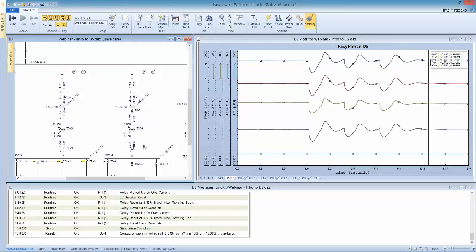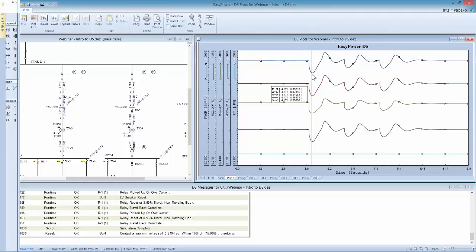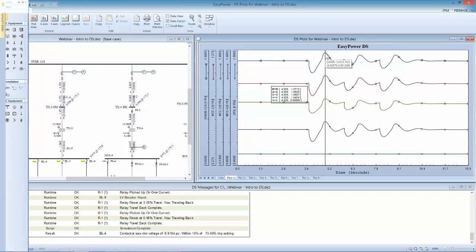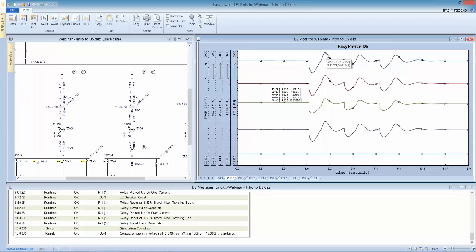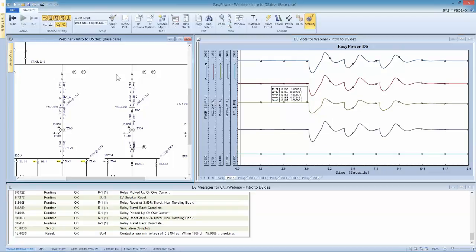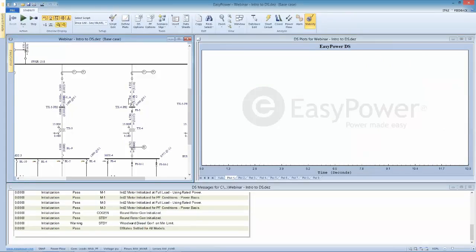And in each case, we see there is exposure to higher than normal or higher than expected voltage. Looks like we're getting up to about 107% of the nominal voltage. And this is a very typical response from an isolated system that's working off of a generator when you have a large motor starting in the line, and how it impacts the rest of the system. So this was an argument, frankly, to go out and evaluate motor control systems that don't go full voltage across the line.